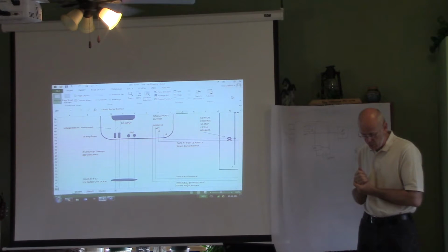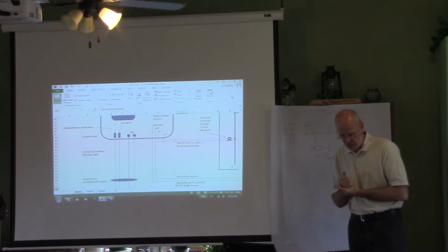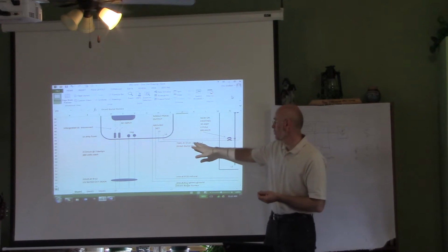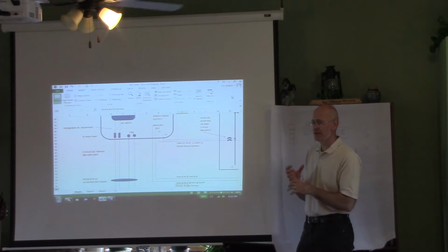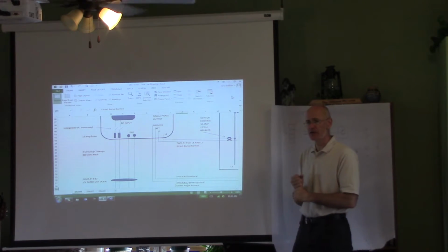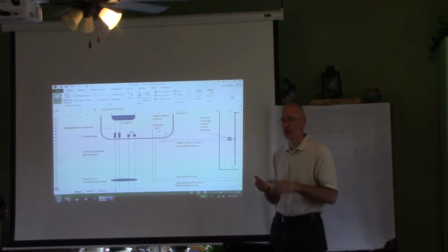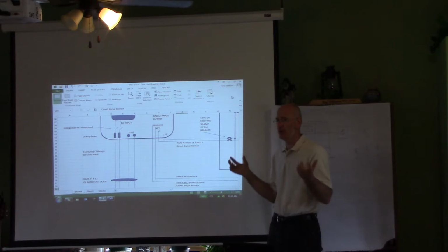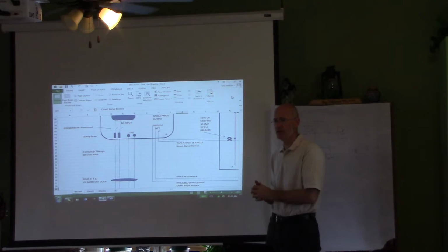We talked about wiring to the inside of the house over to the panel. There's different kinds of wire. Your outdoor wire is UV protected, meaning the plastic that it's in, the sunlight doesn't break down the plastic. Where regular interior wiring, be it straight wire or Romex, you put that out in the sunlight, you give it about 2 years and the thing will just fall apart. I mean, voltage will come right through that plastic and start shorting out.